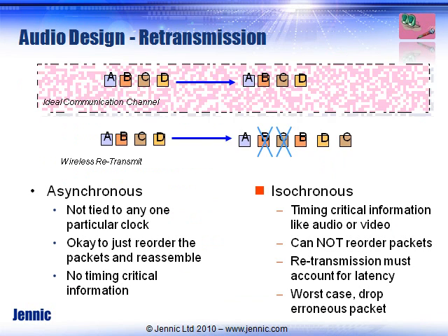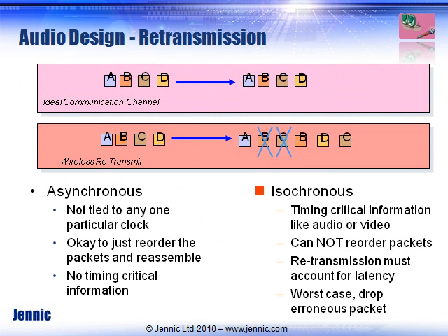technologies do not offer. When you're doing audio designs, retransmission is an issue. The packets have to be ordered and they have to be isochronous. The timing is very, very critical. You cannot retransmit packets and have them be out of order. What we've done with our reference design is an isochronous design for a given application, in this case the audio application, and it gives you very good performance and keeps the packets ordered.